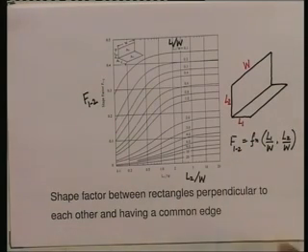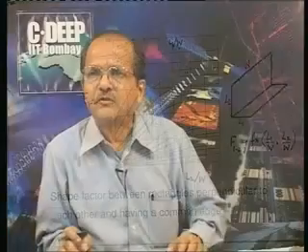Got it? So, again this is a very common configuration, and somebody has done this integral for us and we have got the expression for us to use any time we need it. And like this, as I said, there are literally hundreds of situations for which shape factor calculations have been done, and the values are available either in the form of graphs, equations, tables, whatever it is, they are available to us to use any time we have to do radiant heat exchange calculations.